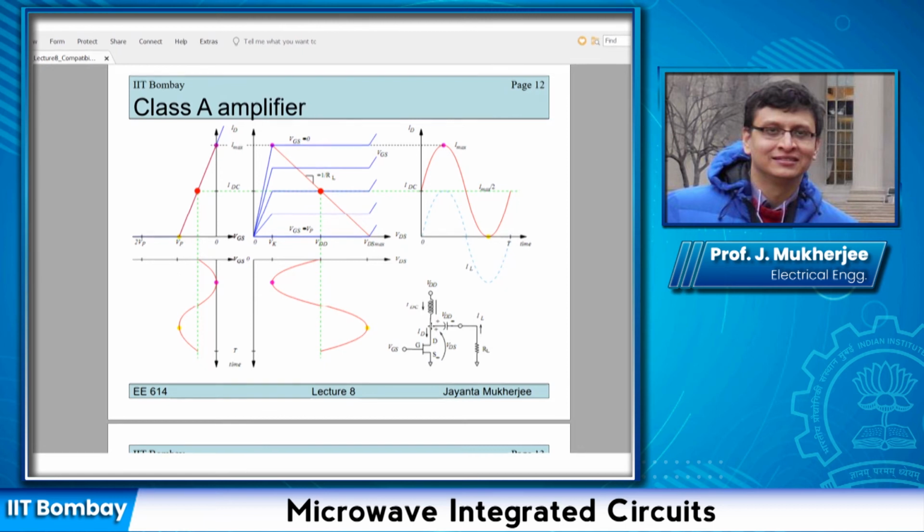Okay, so now that VDS follows the input signal, it is also a sinusoid. This capacitor simply acts as a DC block, and you have this voltage, VDS, which is a sinusoid, appearing across the load. Since the load is resistive, the load current is also a sinusoid.